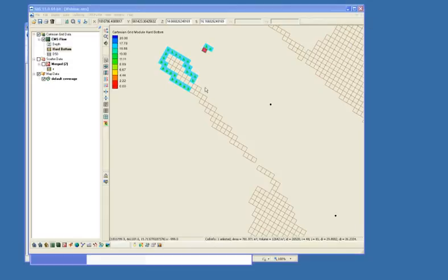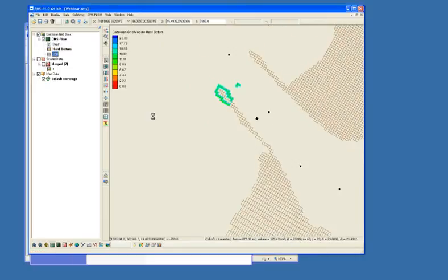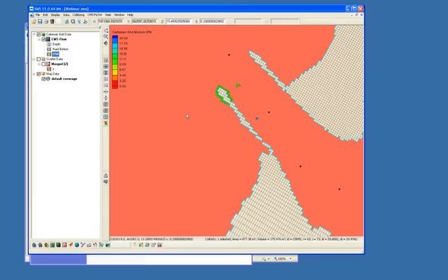Okay, so that's the hard bottom, and essentially the D50 data set is manipulated a little bit the same way. There's no right-click option because you're just specifying a grain size for certain areas. But what you would do, you'd select a certain number of cells, and then you could change this S value in that location to represent that grain value.